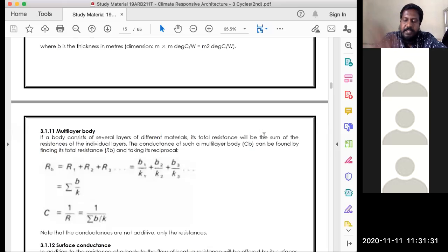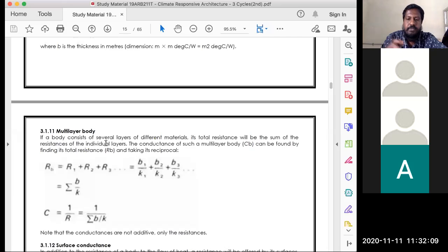So another material is brought in. That has another resistivity value. A glass wool or a foam's resistivity value is much higher when compared to steel. Okay, that is fine. But having this glass wool or foam on an exposed surface is not aesthetically pleasing. So what we do is a plywood paneling or any other surface paneling, which again has its own resistivity. So this becomes like a sandwich of 3 or 4 materials together. In that condition, the total resistance will be the sum of the resistances of the individual layers, that is, the individual materials. That is the way in which you calculate.